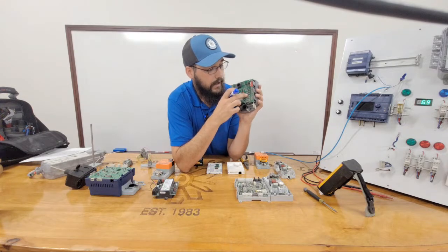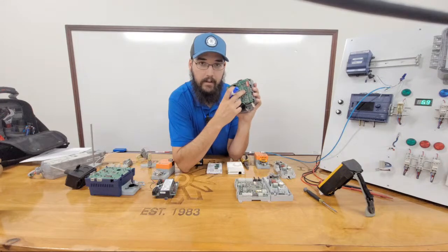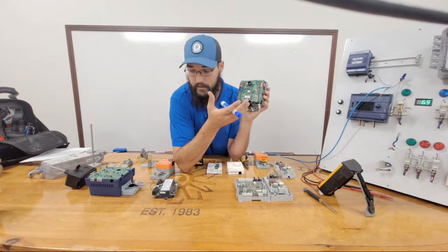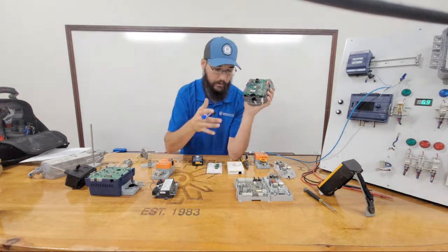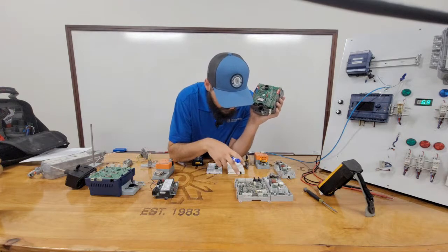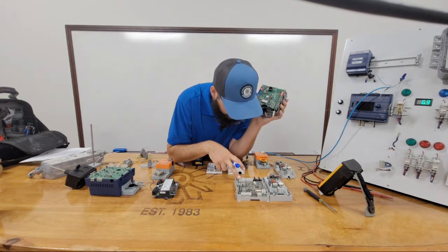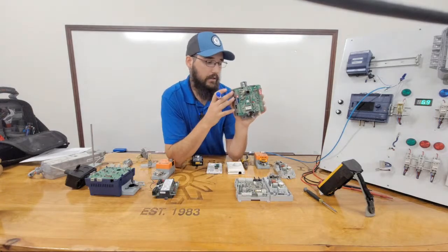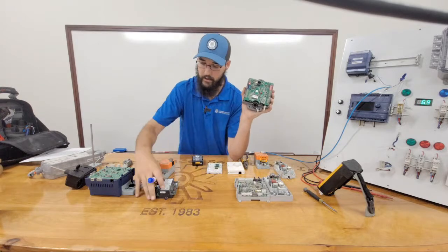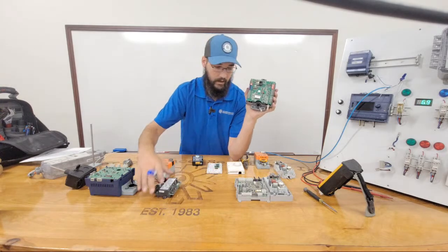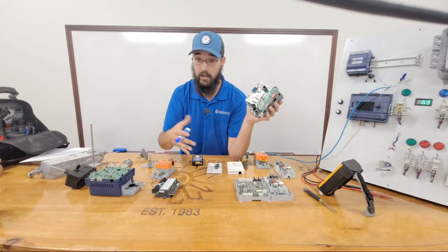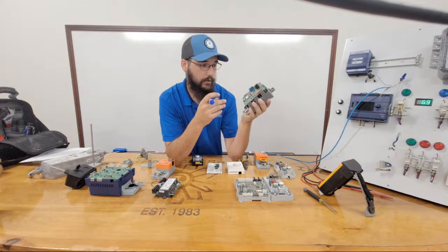The reason I know that is because they have a little triac on there. These triacs are the new relays of today. None of these controllers up here even have actual relays built into them. Just making sure this Honeywell doesn't. Yeah, so none of these actually have it. This is a JCI, or Johnson Controls, controller. We've got an Allerton here. This is a Honeywell, and this is a Distech. So you could see any number of these, and there's a lot more than this that you could run into.